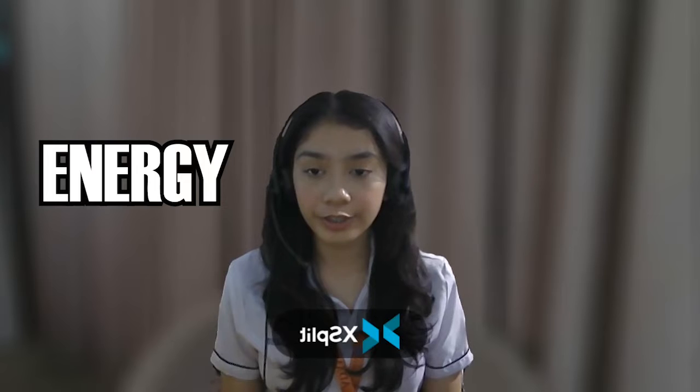Effect of kinetic energy. The influence of kinetic energy on flowing pressure can become significant since it is critical for small diameter tubes with high gas liquid ratios and low pressure levels. The most helpful display of tubing performance for well design is to plot flowing bottom hole pressure versus rate for various tubing sizes and gas liquid ratios. There is a minimum flow rate necessary for continuous extraction of liquids from the well regardless of tubing sizes, which is the rollover point in the tubing performance curves.